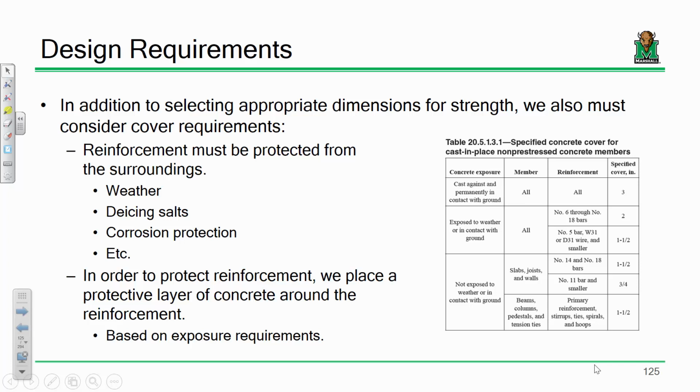Now why would we care about the rebar being 2.5 inches below the top, but only 1 inch from the bottom? What do we put on the top of bridge decks on days like today? Salt. We put de-icing salts, chloride penetration into the concrete increases chances of corrosion. So that's why cover for the top of decks is usually more.